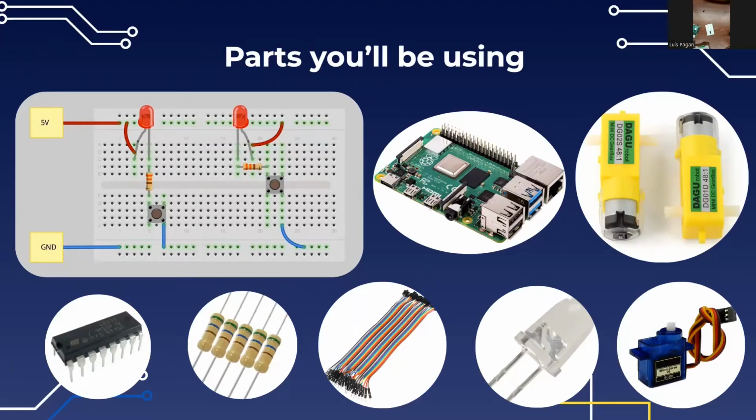To answer Summer's question, the H-bridge is a motor controller that we'll be using to regulate the voltage to the motors, which allows us to change the speed and the direction of the motors. This is much easier than wiring something up yourself, because most likely you're just going to be doing it in one direction. You could change the speed, but it's a lot easier to use a motor driver to do this for you. We'll get into how to control it later on in the workshop.